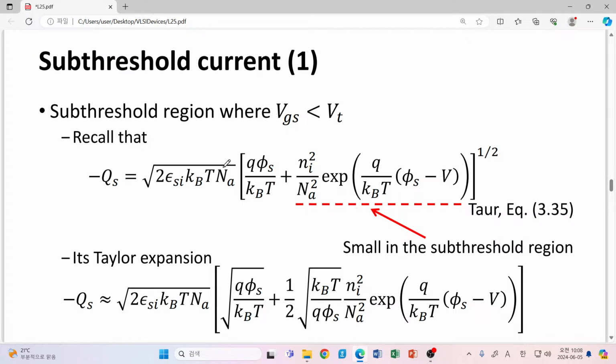Okay. The final thing we have to cover is subthreshold current. Subthreshold means simply that the gate voltage is lower than the threshold voltage. If we further reduce the gate voltage, then we enter into the accumulation region, but practically we don't use accumulation at all.